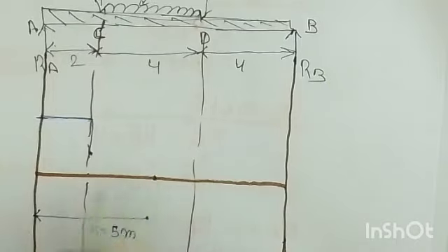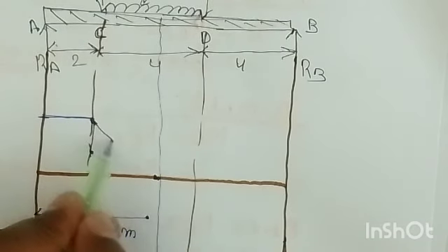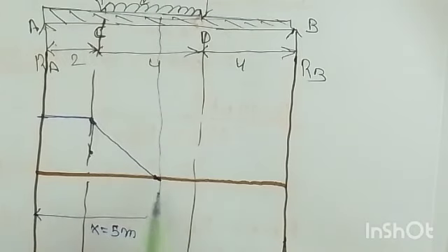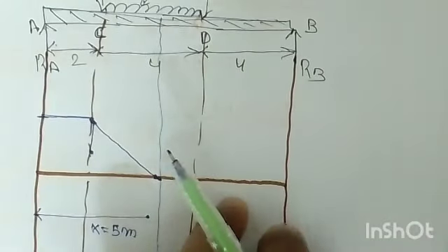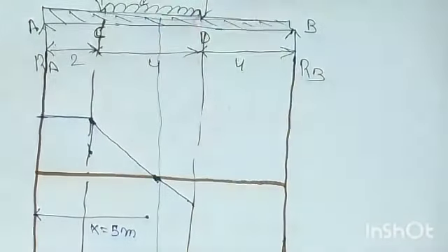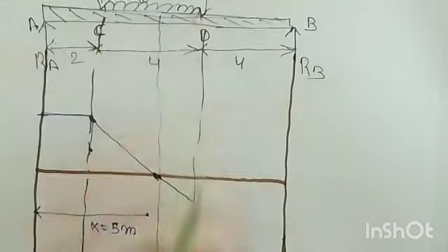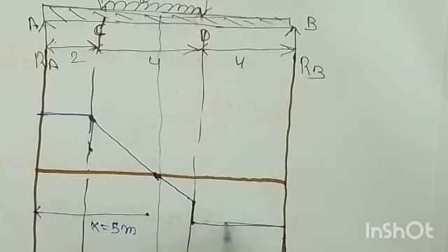So it means that here the shear force is 0 and the bending moment will be maximum. And then it deviates like this, it becomes 0. Again, the shear force just LHS of D is what? That is minus 10. And then just RHS of D it will be 40. So this is 50, and this will remain constant like this.